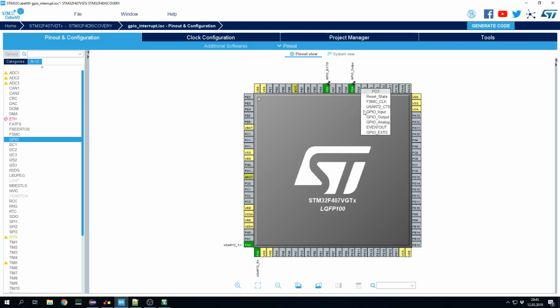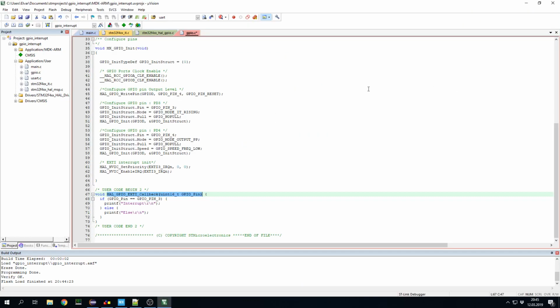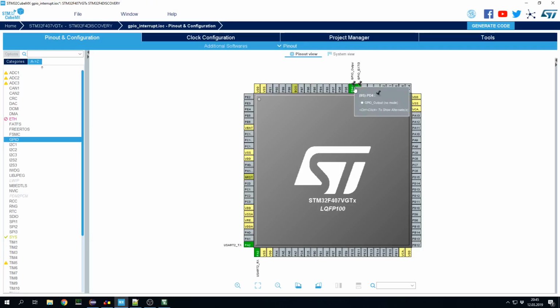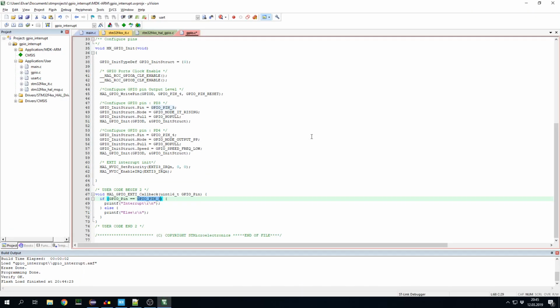So you cannot choose both of them. You won't have any problems here if you compare with GPIO pin 3, when it will be the pin 3 you selected for interrupt. And as you can see, there are like 16 different possibilities to do the interrupt, so there should be enough pins for you.